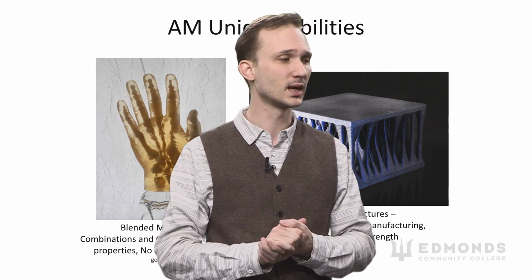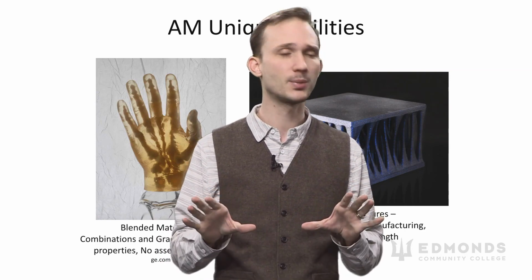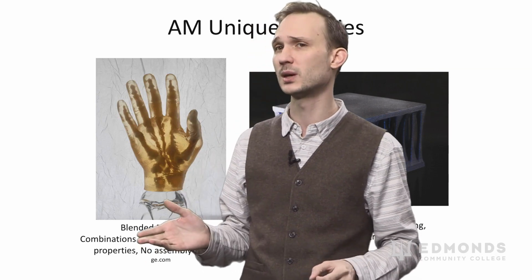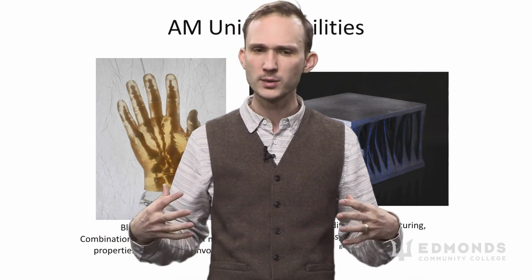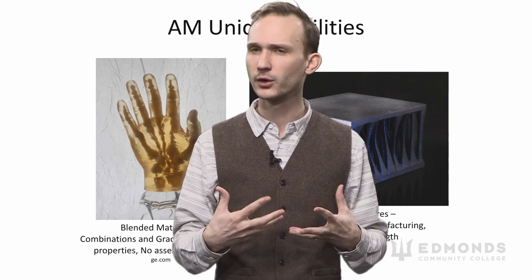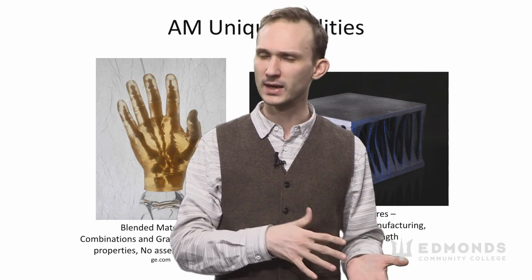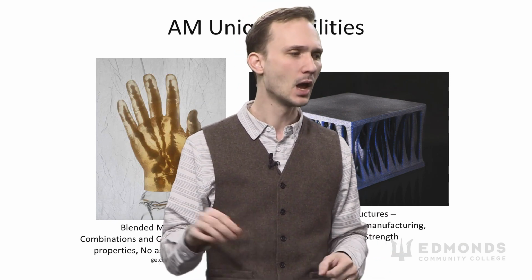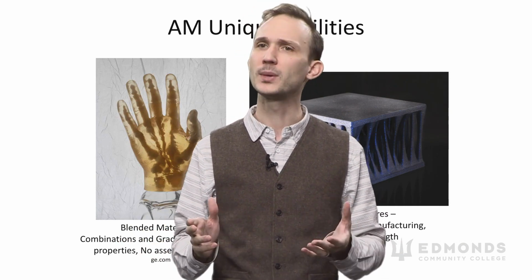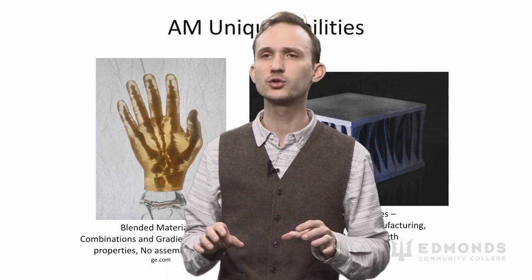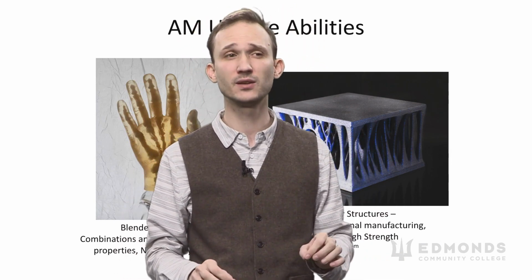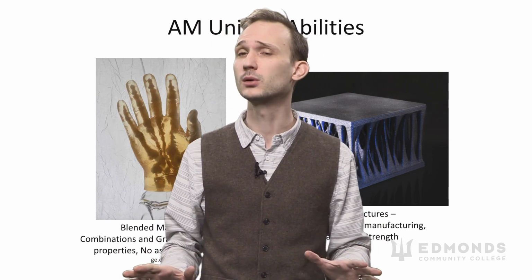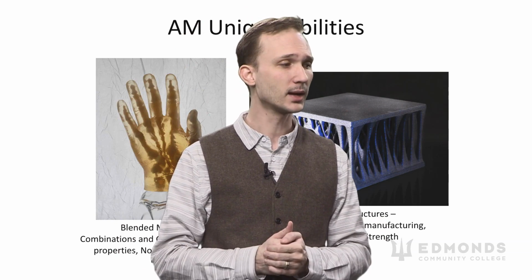We're going to take a look at a few examples of that, but the most important things to keep in mind are that we can leave internal spaces where we decide to do so, especially with fused deposition modeling. With other methods, we may trap our excess material or uncured material like resin or powder, in the case of powder metal printing, inside of those empty spaces, but with fused deposition modeling, we're only trapping air inside. We can also produce trabecular structures, things that would be uniquely difficult for subtractive manufacturing to make, and perhaps impossible for formative manufacturing to make.